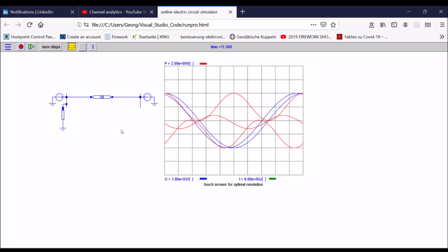So how do you establish now the phase angle difference between these two sources, which you can see here? Here I have the curve from the source on the left, and here I have the curve from the source to the right. So this phase angle difference, this is what creates the power sharing. How do I establish this phase angle difference? By the torque. So as soon as I start to increase the torque, I push more power, then I increase the phase angle, and then automatically I get more real power from this source to the real power needed somewhere.